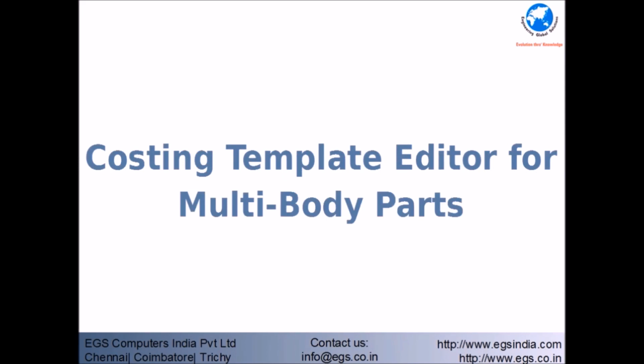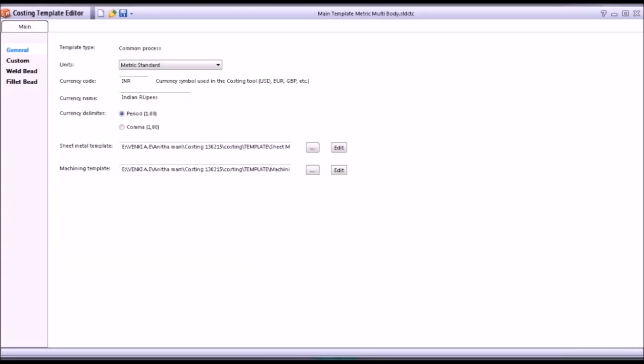Costing template editor for multi-body parts. Use the costing template editor to create and edit templates for use with the costing tool for multi-body parts. Contents. General: use the general screen in the costing template editor to set the units, currency and template location options.